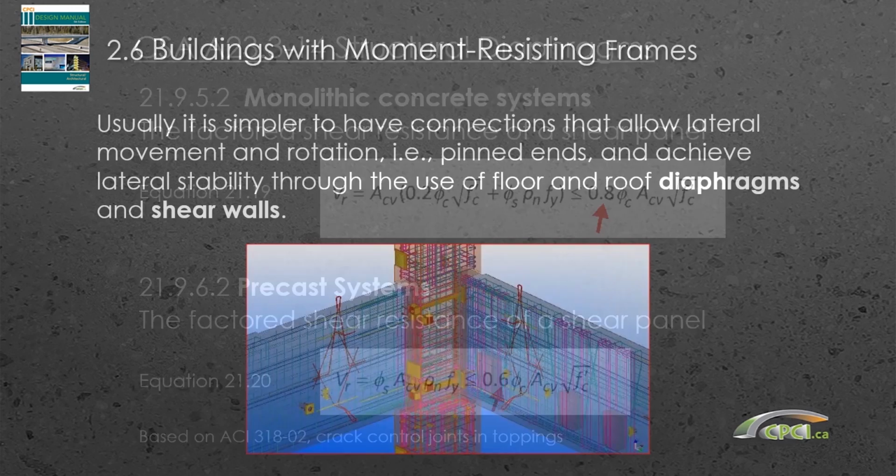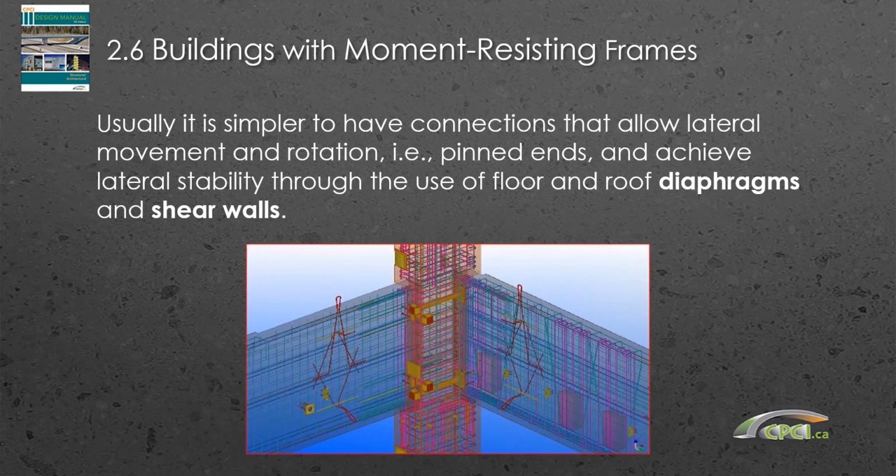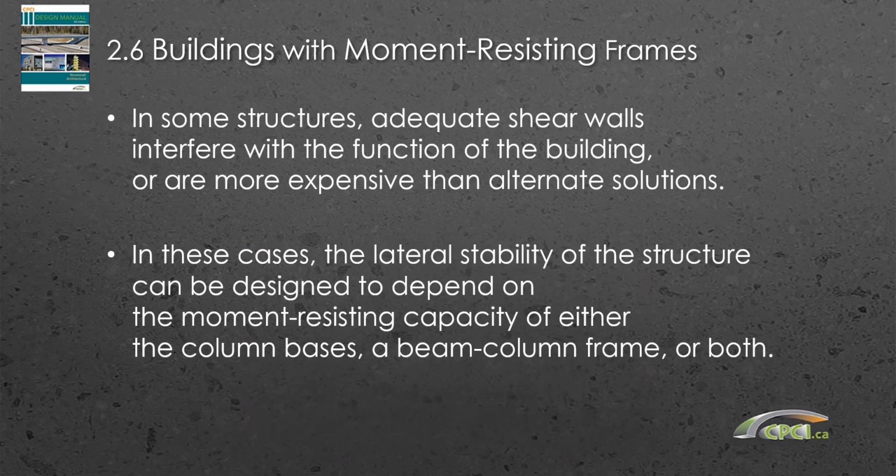So there's a section in the manual on moment resisting frames, and it's simpler to have connections that allow movement and rotation, but if you need a moment resisting frame, there are some examples there of how to handle that. And I guess the big picture coming out of that is you really want to limit the amount of moment resisting frames if you can.